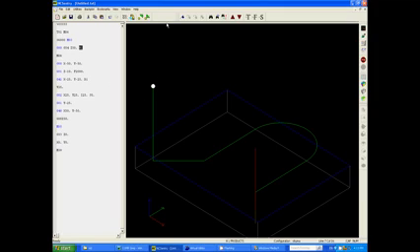So it will automatically calculate to position the base of the cutter at 50mm away from the top of your job. Now the next line of code is an M08. That simply switches the coolant on. So an M08 will switch the coolant on and an M09 will switch it off.